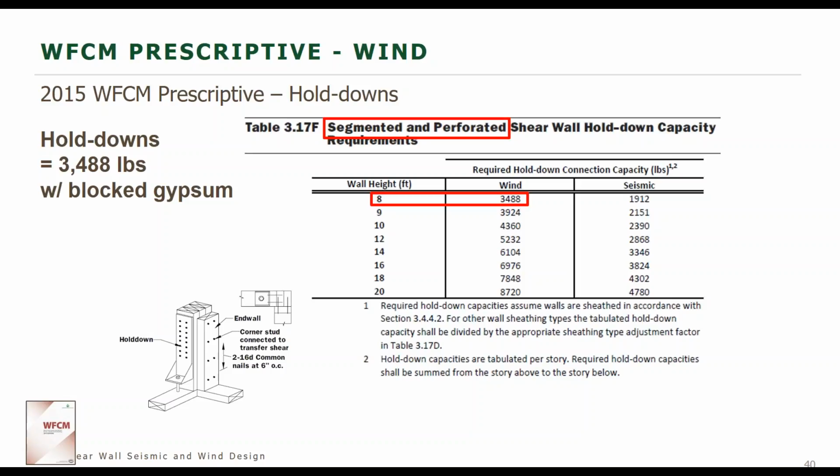Oh, yeah. We didn't cover that today, but the wood frame construction manual allows the use of wood structural panel sheathing to resist both shear and uplift. Instead of straps at all of your studs, you can use the wood structural panels, and then the anchor bolts could carry the loads into the foundation, and that would also apply between floors.